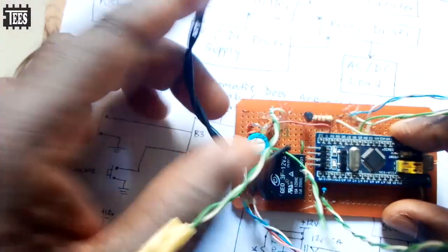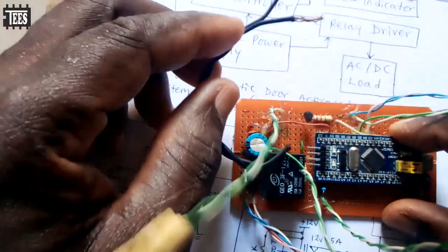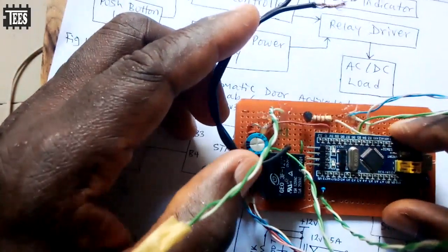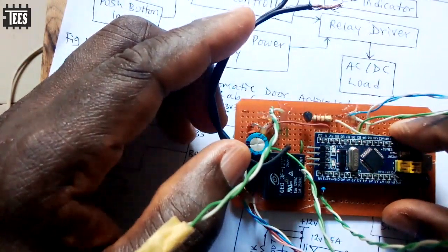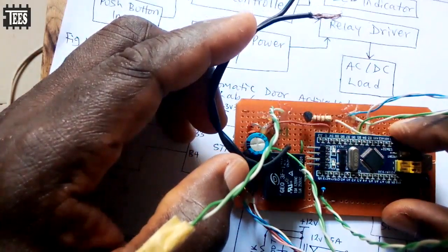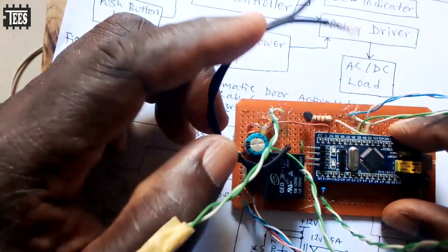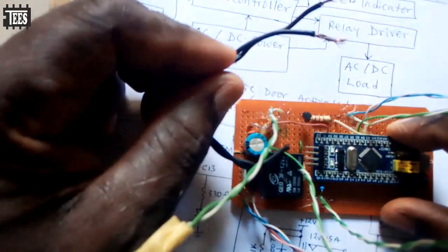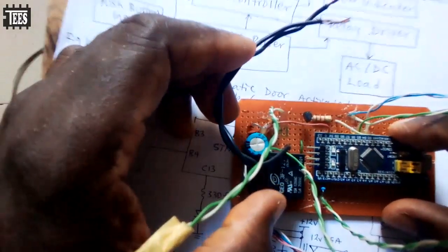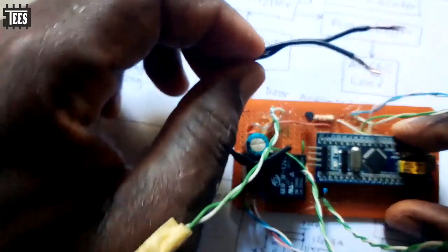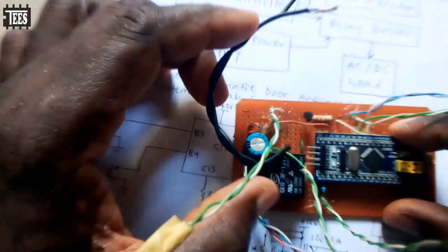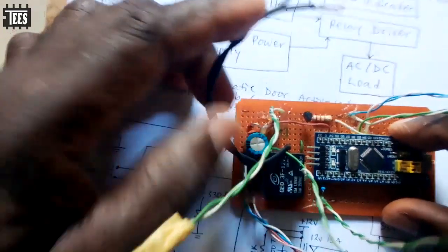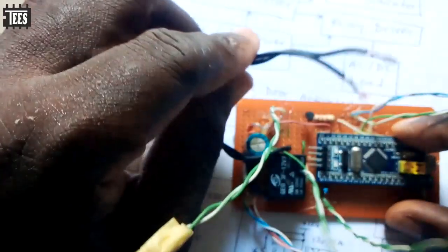You understand? Like for this relay now, I can use this to power my appliances, but if I'm going to use this to control the power to cut off or link up power to my workshop, I'm going to use this relay to power a contactor, a bigger relay. You understand? So if your load is less than 15 amps, you can just use it directly. But if your load is, let's say, something around 100 amps, everything in your workshop, then you use this relay now to switch the contactor.